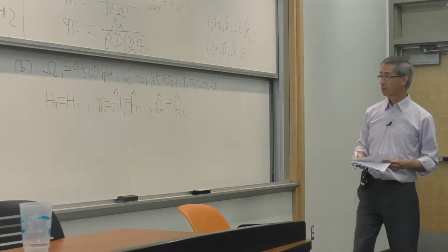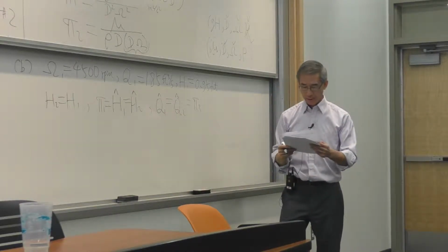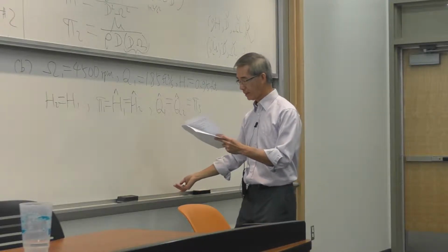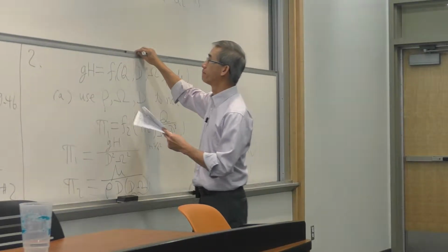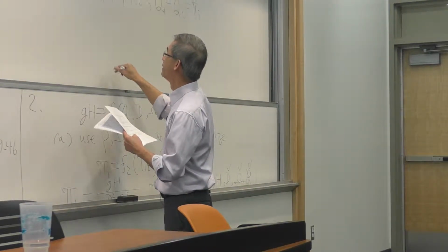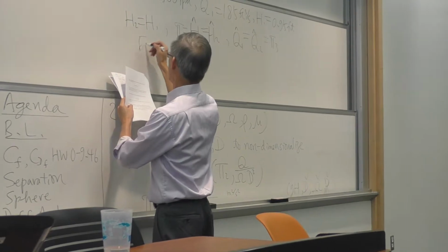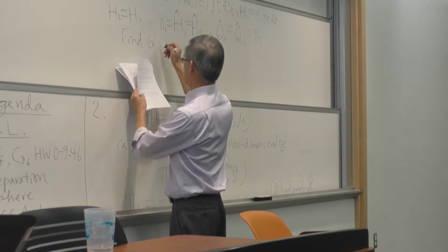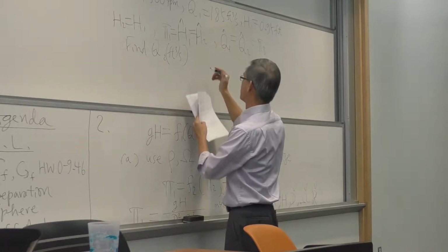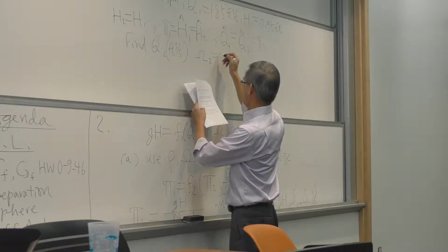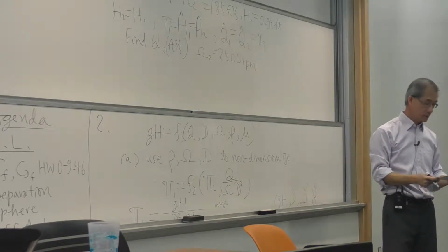And my Q, you can call it the pi 3, which is given, must also match, such that using those conditions from part A, with the pi 2 term known, find a new Q2 in feet per second, where my rotational speed for the new pump is 2,500 RPM.